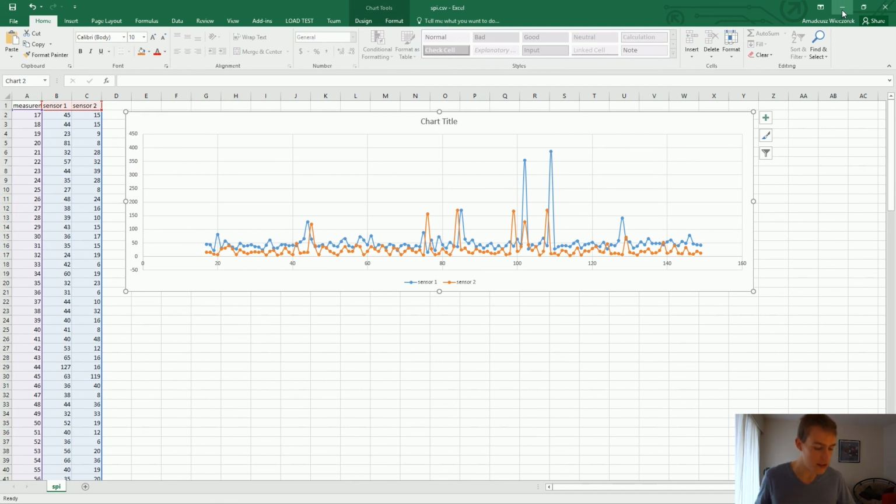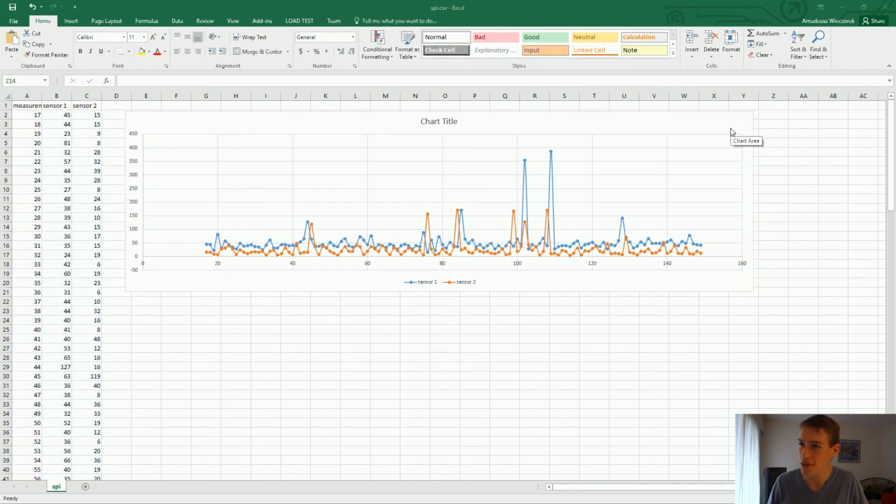Also, the distance between the measurement and the microcontroller should be very small. And here I have a connection using 3 wires, so there's definitely a lot of noise, and I'm pretty confident that in a smart mirror, in a final product, the noise will be much smaller. However, for what we need now, we can see that if the measurement is over 100, then it's probably a valid measurement. Alright, so this is our data.